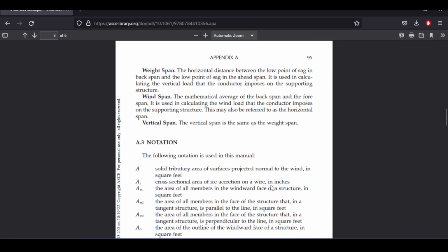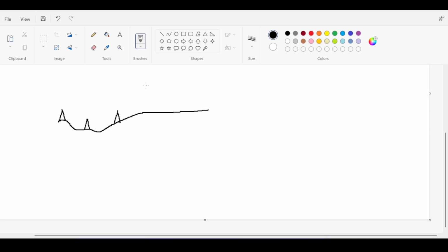So since those things change, you need the input of your surveying team or your own input. You need to know the longitudinal distances that you are going to cover with your cables. And this might be given to you or this might be something you will have to do. If it's given to you, then perfect. If it's not given to you, then you have to do it yourself. Also notice that this span is different than this span. So each tower has its own span.